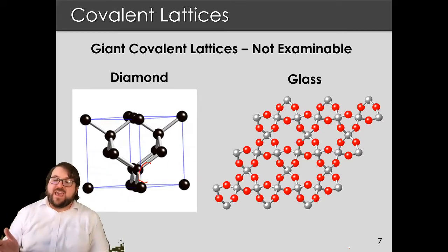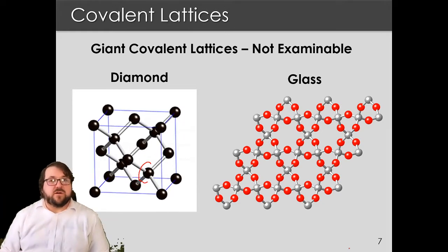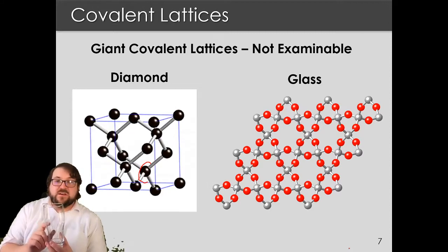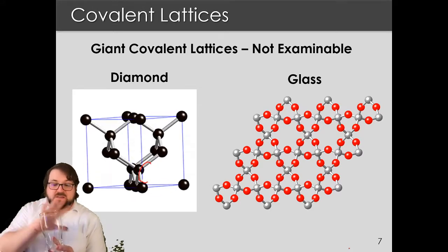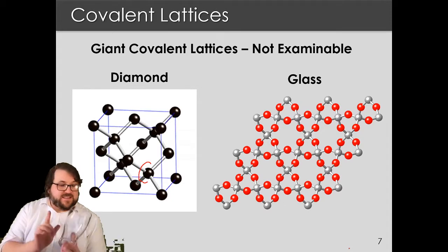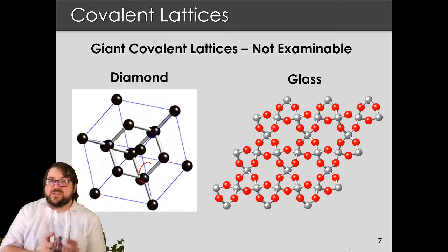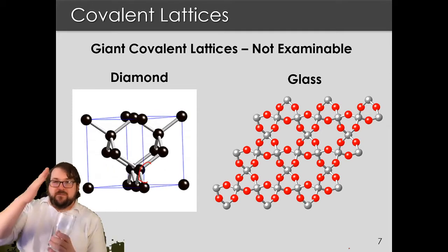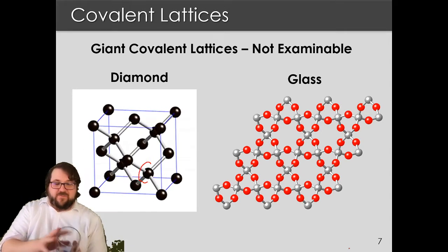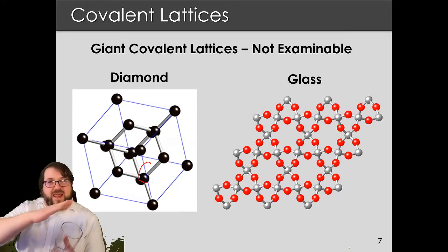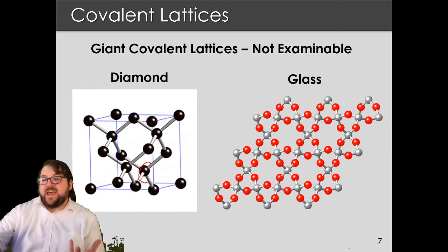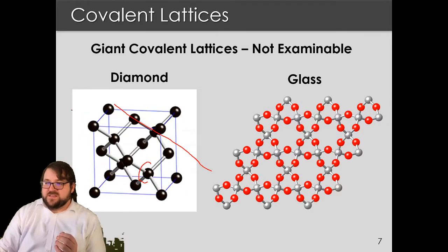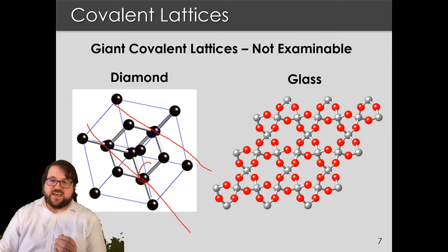So it's not always the case that long-range order is what conveys strength to it, but part of the reason that glass is so brittle and fractures so easily is because of the disorder inside its system. It still has the same strength of bonds as diamond does, but it does not have the regularity of it. That means that when it fractures, it can sort of fracture in any place because it doesn't have to find a plane to fracture down. When I say a plane, I mean, for instance, all of those atoms need to detach, or all of those atoms need to detach.